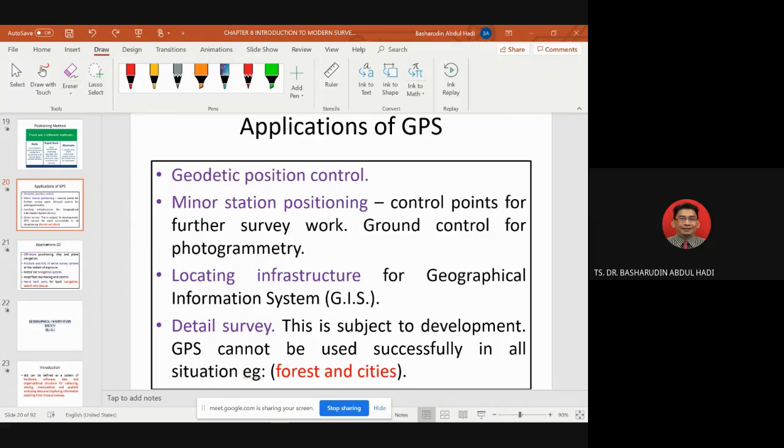When they fly, they need ground control points that can appear clearly on their image, because they want to know that point's X, Y, and Z. If they know that point, through photogrammetry fundamental knowledge you can calculate everything, like the tree heights and the contouring, but they just want to know the first point.